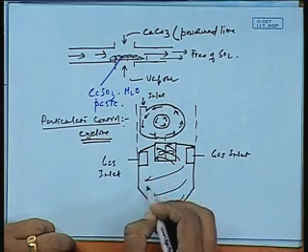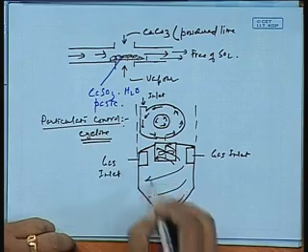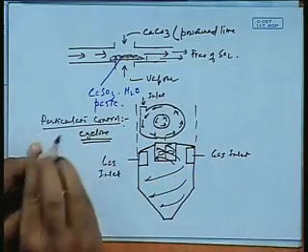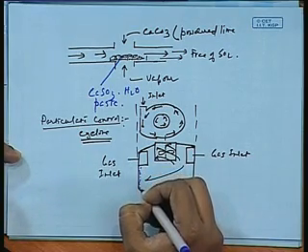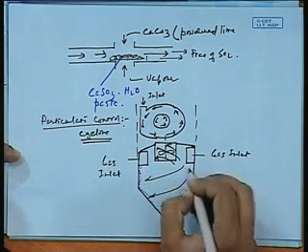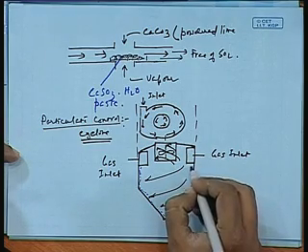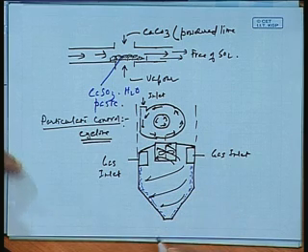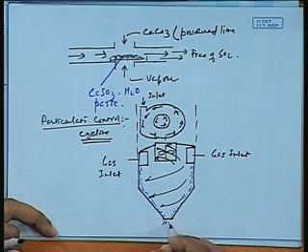As a result of the centrifugal forces, as you know, the heavier particles would go across towards the sides. So the heavier particles would be clouding here, and they would impinge on the outer surfaces. Many of them would begin to go down like this, and this is where they would mostly come out.